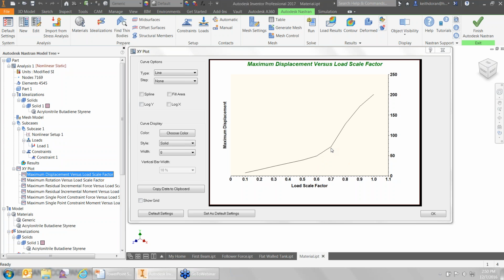And in our reality, if I were trying to figure out where this component was going to yield under the load, I could do a couple of different things. The first thing that I could do is change my analysis type to a nonlinear buckling. And with the buckling, I can then specify essentially what frequency to magnify my load. And then in this case, I would probably just apply like a 100-pound load as opposed to 1,000 or 500, and then say increment this by a factor of 1. So it would just go 1, 2, 3, 4, 5, and so on.